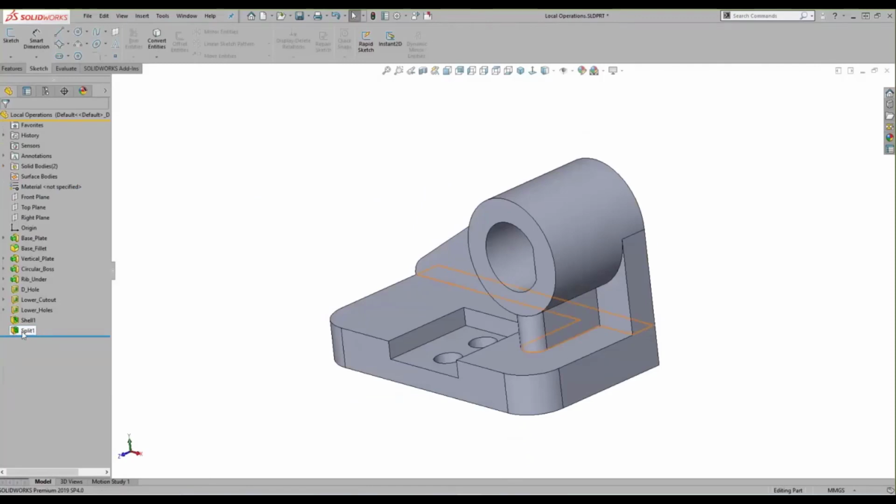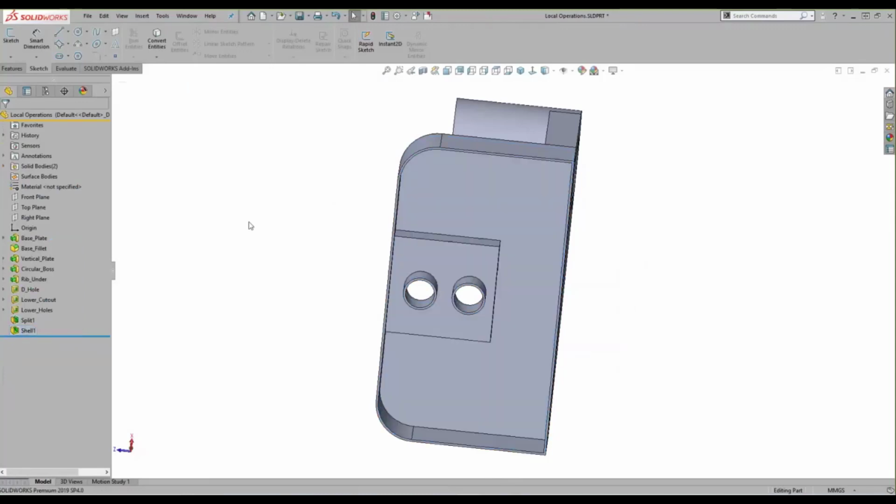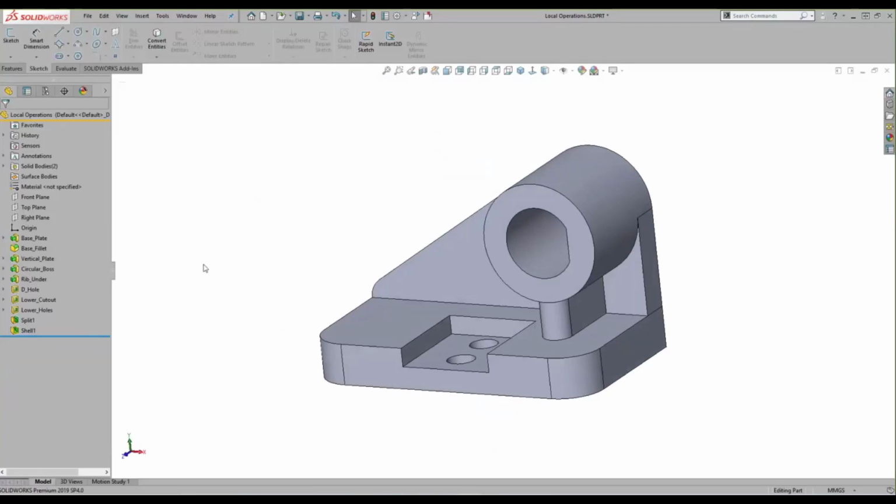That's okay. Thankfully, we can take these features and leverage what we did learn in Essentials to reorder the feature manager tree. We reorder the split before the shell, and because the shell can only interact with one solid body, that's all there is to it. And it's 11:28, so even with my mistake, I get the part off to my manager and I make my design review. So just a different way of looking at these modeling situations.